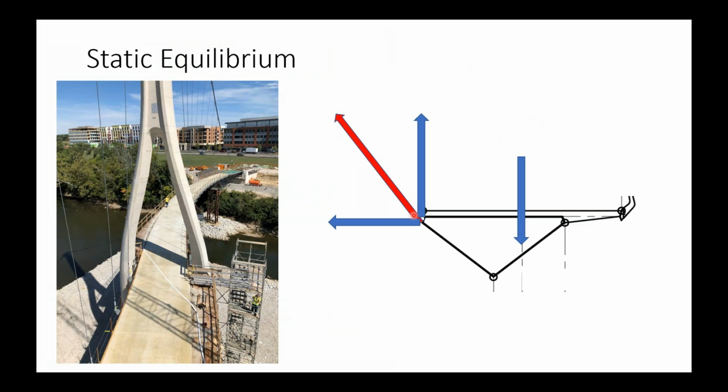So we saw the configuration, and I mentioned earlier that we've got a single pylon and a single main cable, and the implications of that are that we've got a single plane of hangers. We've attached those hangers to the inside edge of the girder, so that the hangers are all inclined outward, leaving plenty of headroom over the deck and a nice open feeling on the deck. As we saw in plan, there's an S curve in the deck, and so the inside of the curve on the other span turns to the other side.